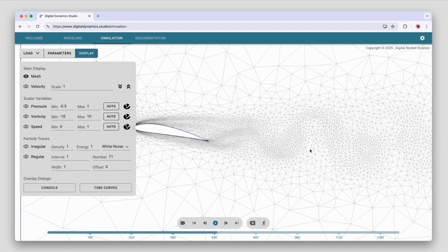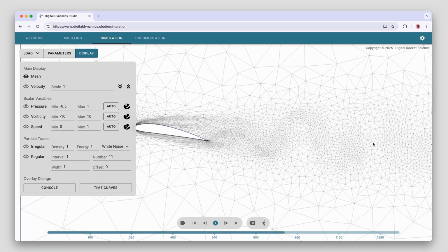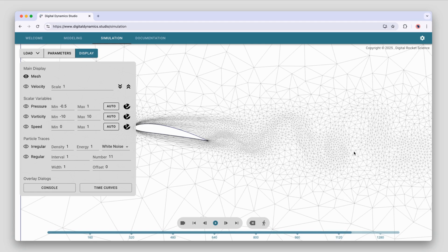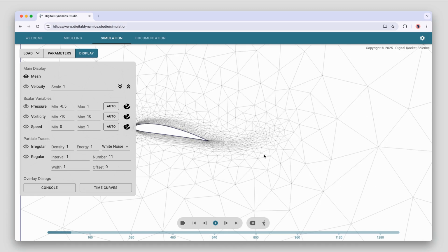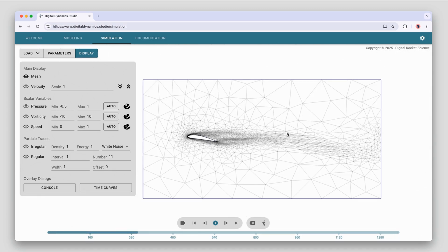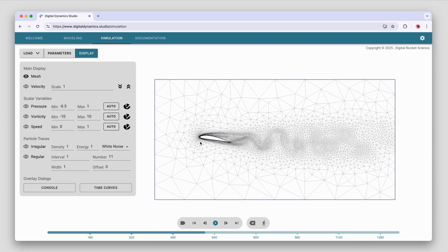You can see the mesh. You can see the adaptive algorithm happening here. You can see how the mesh is changing its structure, density and sizes to follow the features of the flow. This is done so that as much as possible, we can ensure high accuracy of the results everywhere in the domain at all times. You can see the adaptation extends throughout the entire computational domain.